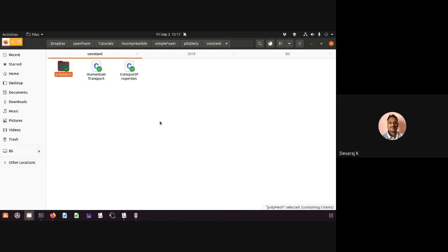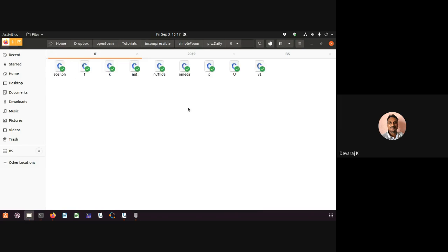So usually your epsilon, k-epsilon, omega, all those things, as I told, if you go to this particular thing, look at this. All your turbulence property files are written in this particular system. In the constant folder, sorry, the 0 folder actually, that is your initial condition, all your files are here. Epsilon, k and all are defined here.